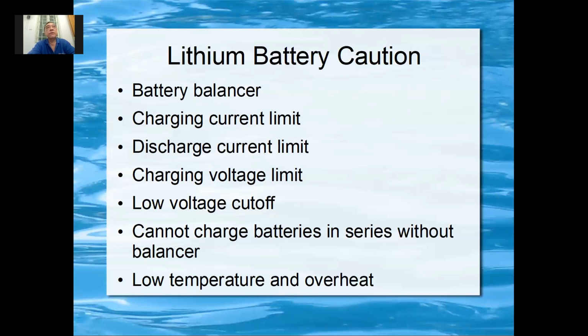And if you have 2 12-volt lithium batteries, you don't connect them in series. Okay, when you want to charge, you can charge them separately. That means you disconnect them, treat them like 12 volt, put them in parallel and charge. Then both will get fully charged. Put them in series and treat them like a 24-volt battery and charge it, then one will get fully charged, the other one will be undercharged.